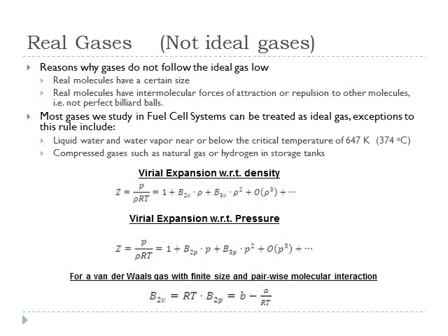And just note, Z is non-dimensional. It's what you take as P over the density times RT. For an ideal gas, it's equal to 1, but for real gases, it's not equal to 1. It can either be greater or less than 1. It's always going to be greater than 0, though.